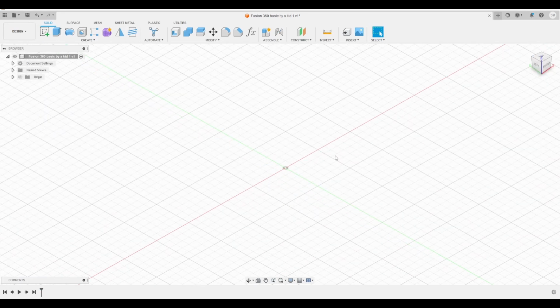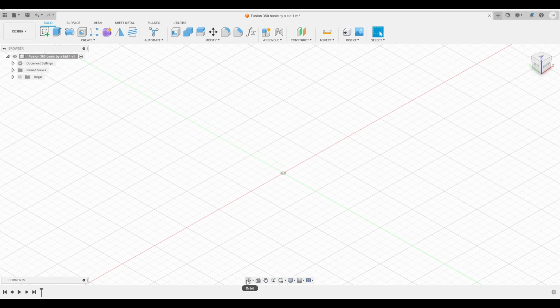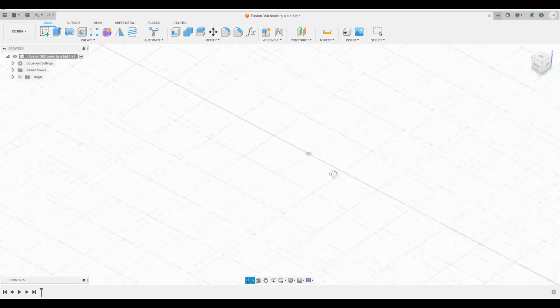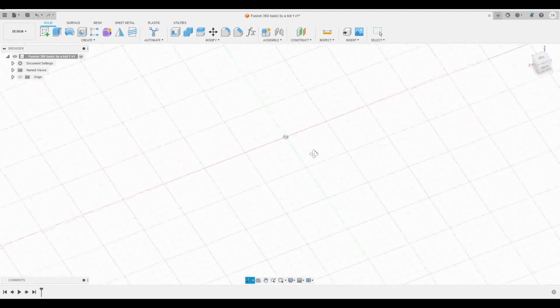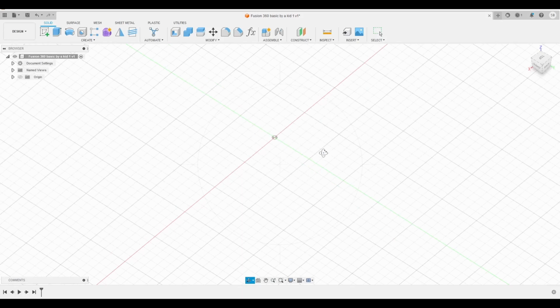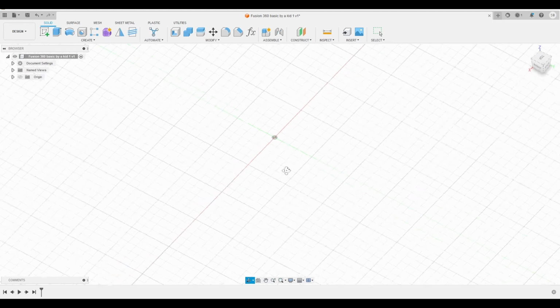The second way to move yourself around the 3D plane is using the tools at the bottom of your screen. The good thing about them is that each one of them has a personalized shortcut. The first tool we have is the Orbit tool. It will help you have a quick look around a certain place you click. The shortcut for it is pressing Shift on your keyboard plus the scroll wheel on your mouse.